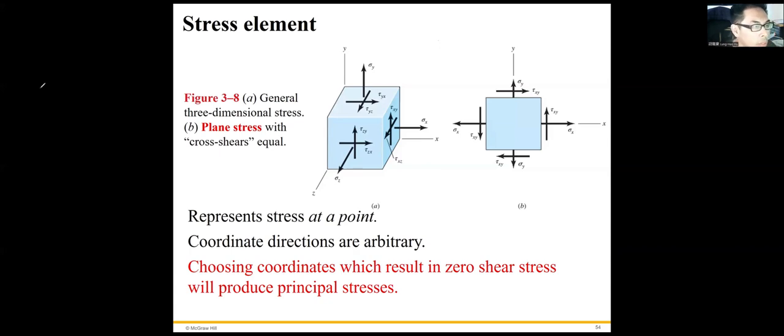Okay, so today we are going to discuss the 3D element which is subjected to loading. Any loading can be axial loading, or torsion, or bending, and so on. If we look at a small, infinitesimal element, this 3D element should be subjected to the normal stress on each surface and the shear stress on each surface,